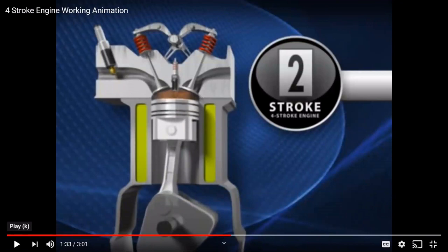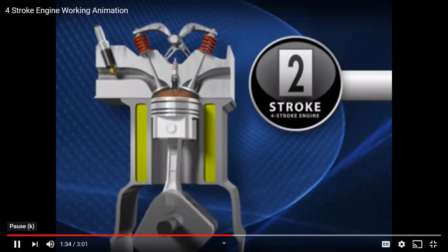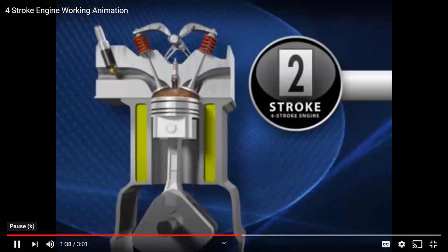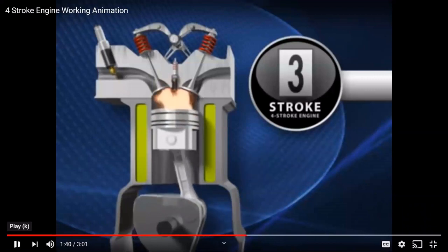And now, even though you're going to see the piston move a little bit, pretend the piston's not moving. And as you watch all the fuel ignite, that is the isochoric process that goes straight up the PV diagram to higher temperature and higher pressure. This is called the compression stroke. At this point, the spark plug fires, sending the piston downward. Okay, it moved a little bit. Just ignore that. Pretend that's isochoric.